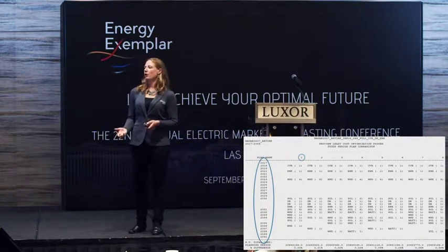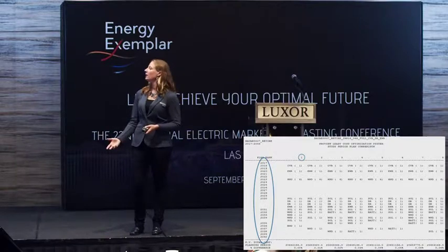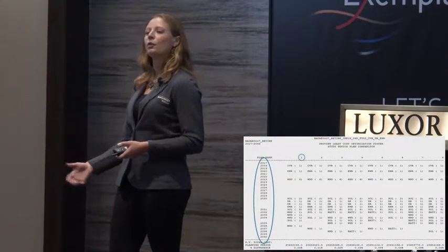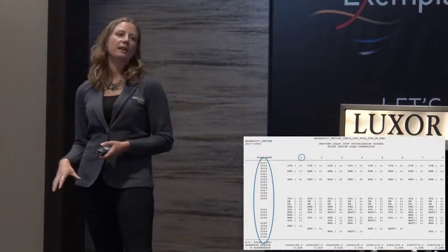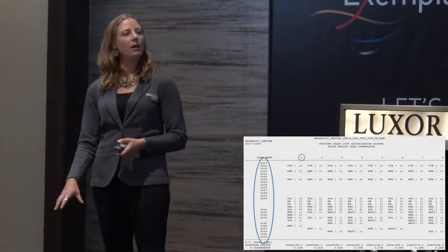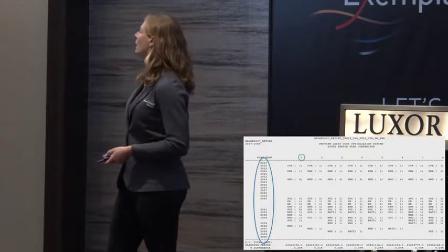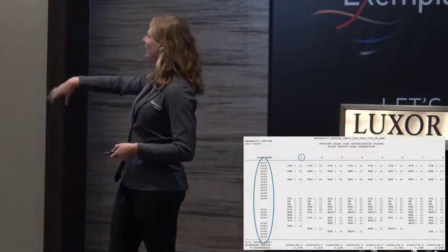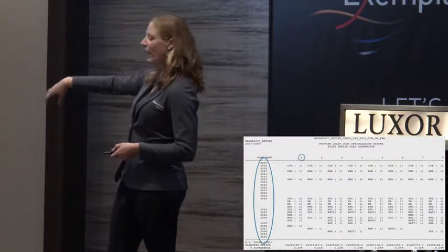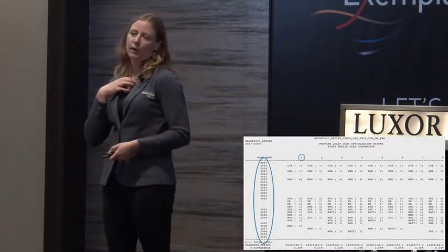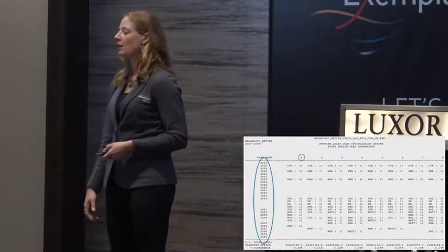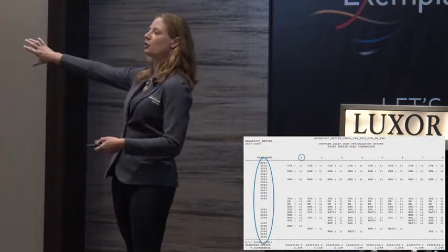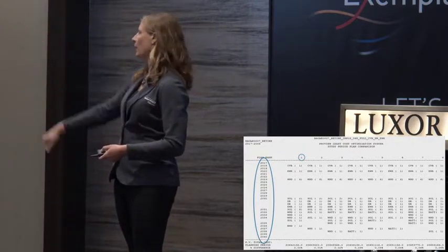So in any years that there is a need within our study period, Strategist is obviously selecting the most optimal resource from a cost perspective to meet that need, because Strategist is a least cost model and a least cost model only. So that means our optimal plan, you can see, is a renewable heavy plan. In your outer years, which is where we were seeing the most need in our IRP, you're selecting some solar, some wind units, and again, demand side is being chosen upfront and very quickly.